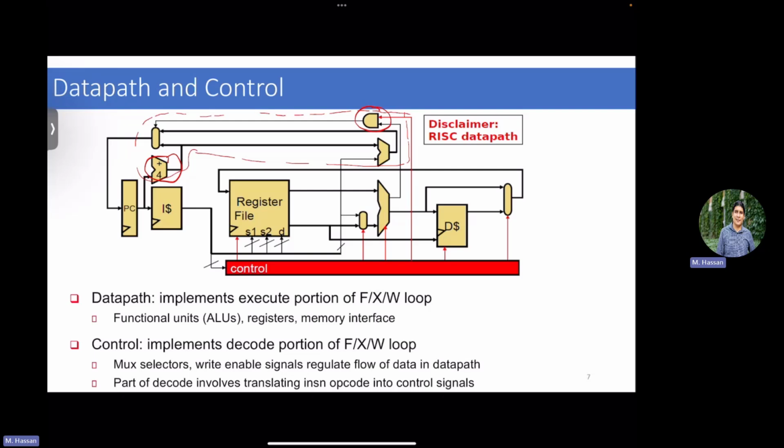Because if you cannot read a new instruction every cycle, everyone else has to wait, right? Fetching instructions from the memory is in your critical path. That's what you are going to operate on. If you don't have an instruction, you cannot do anything, right? So this is the part that you want to really maximize as much as you can. Good. This is why we have an instruction cache. So I use the program counter with whatever its value is, whether it's program counter +4 or my new program counter for the branch, as an address to go to the instruction cache to bring in a new instruction.